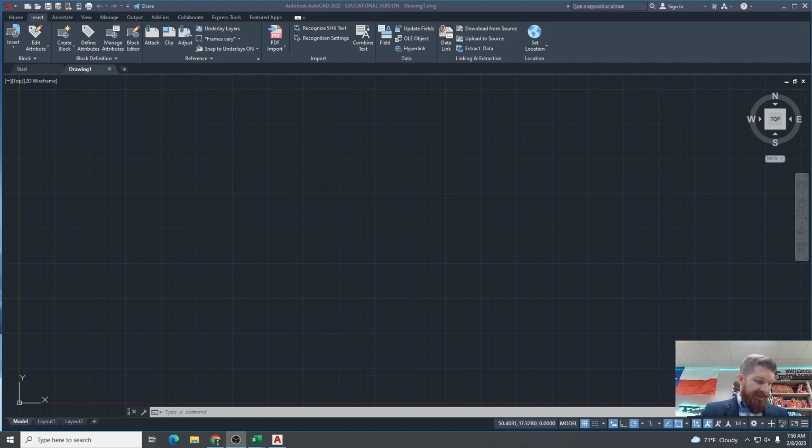So, objectives. We are going to be able to draw projection lines using ortho, snap, and polar tracking. Be able to use X-line, ray, and offset to create construction lines. Be able to use object snap tracking for alignment of the lines and views. It's very important that all of your views line up and they're the same size. Be able to use construction layers for managing construction lines. Be able to use line types, line weights, and layers so that we can draw everything to those ANSI standards.